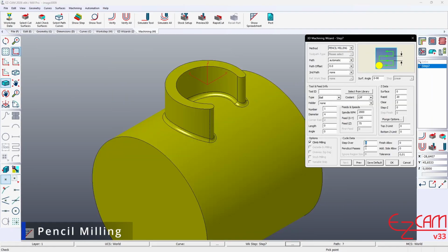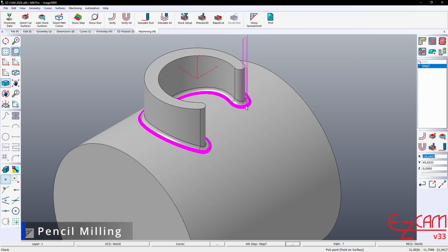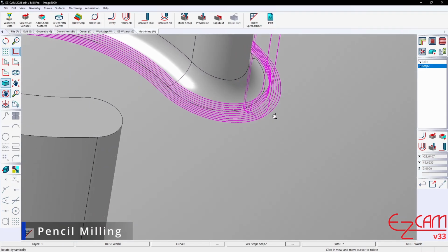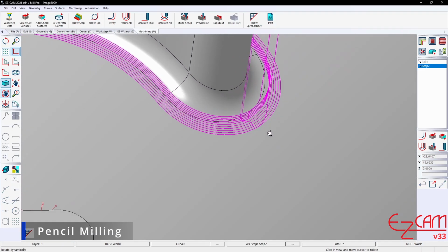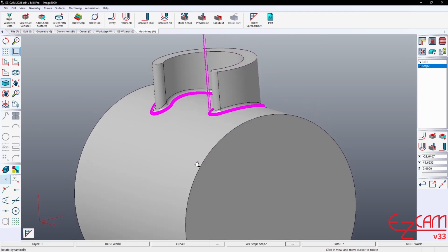Corner machining enhancements. To provide more controlled machining in regions with fine detail, multiple corner-specific pass options have been added. This lets the tool work without strain in small radius corners, helps achieve smoother surfaces, and significantly extends tool life.